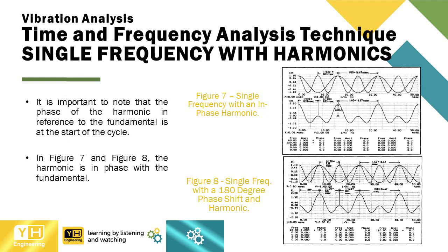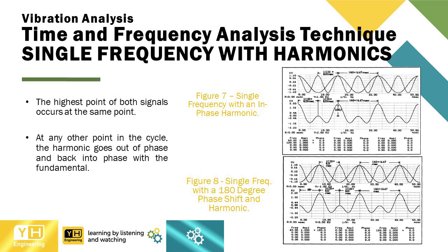It is important to note that the phase of the harmonic in reference to the fundamental is at the start of the cycle. In Figure 7 and Figure 8, the harmonic is in phase with the fundamental. The highest point of both signals occurs at the same point. At any other point in the cycle, the harmonic goes out of phase and back into phase with the fundamental.